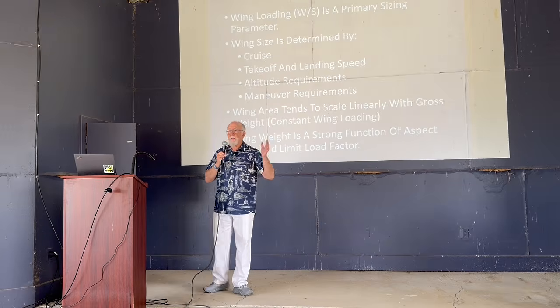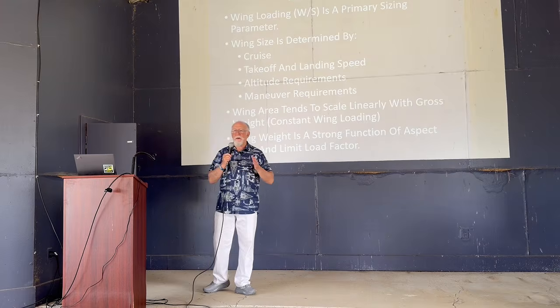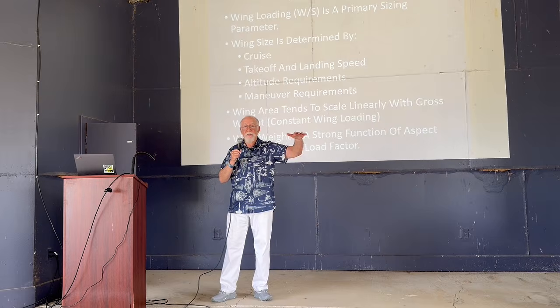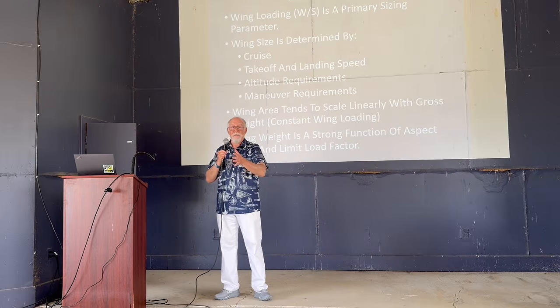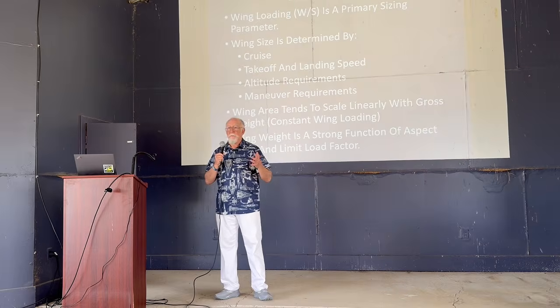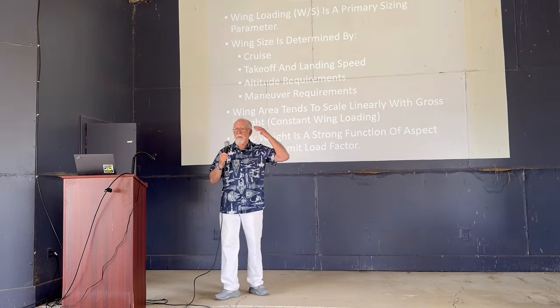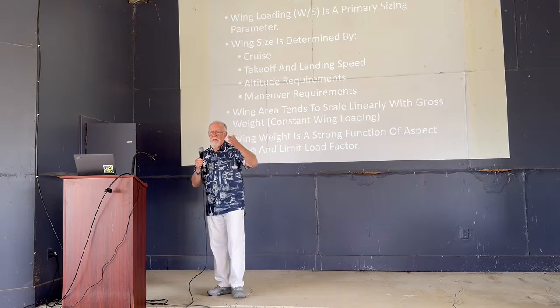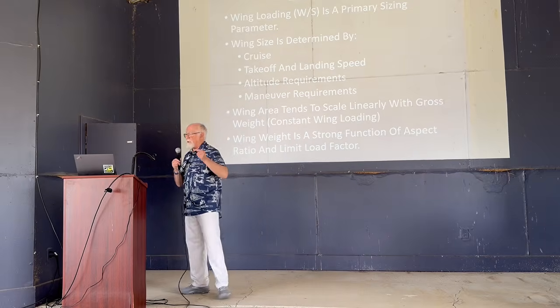For example, if you're certifying under either Mosaic or Part 23, there's a stall speed limit at a specified configuration. That'll set your wing size, almost for sure. Part 23 is 61 knots with the flaps down at gross. Mosaic, depending, has a few stall speeds.